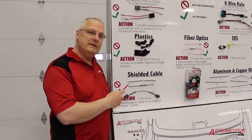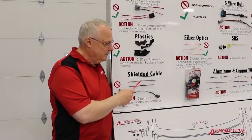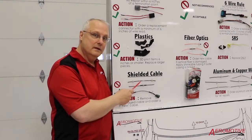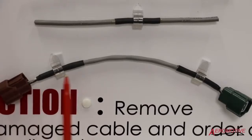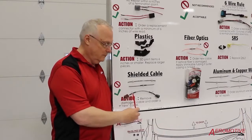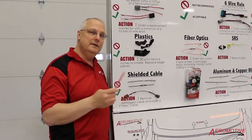What do you do when you have a damaged cable? Well, as long as the damage doesn't exceed 1 inch in length and you don't have more than 25% of the shielding missing, you can apply shrinkable tubing. If you exceed this limitation, Aeromotive can manufacture a complete shielded cable assembly with connectors on either end, or just the assembly itself. So there are some alternatives for you, some repair options, but again, you need to know your limitations.